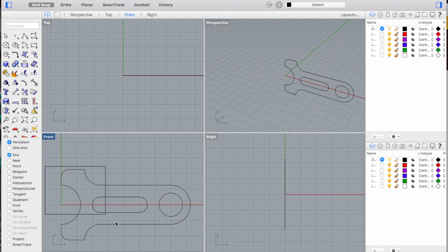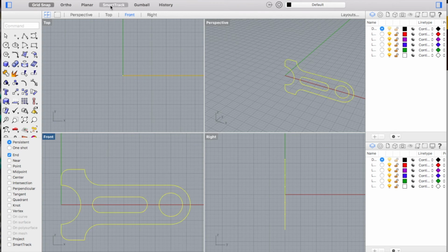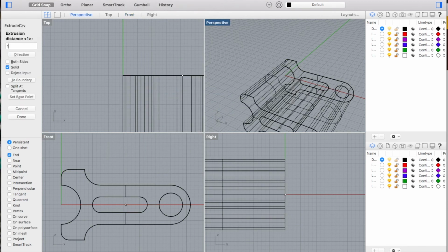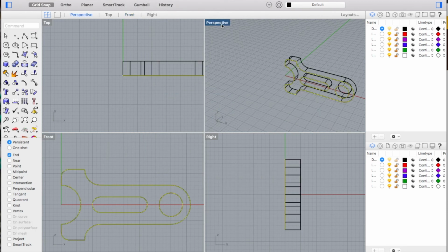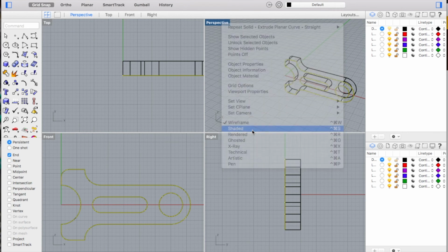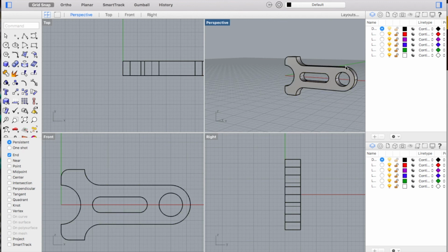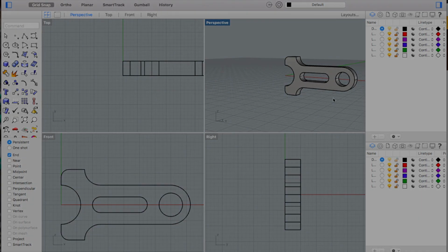Select it again, because now we're going to extrude it, and the instructions tell us to extrude this for 1. And if everything went well, we should have a solid object here. Again, if you have just the outlines but no solid part of the object, you got a gap somewhere, and you're going to have to either redo that or try to find it and fix it. So that is it for exercise number 28, practice with arcs 2.